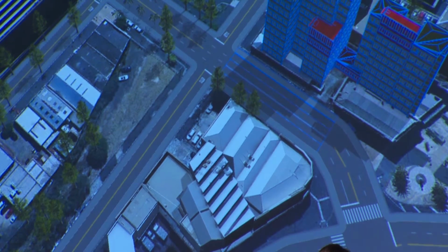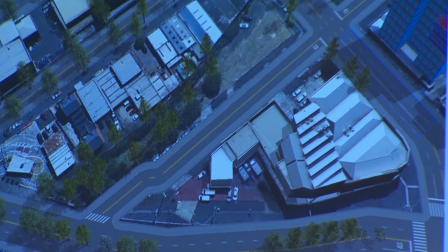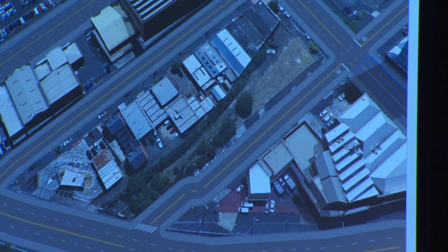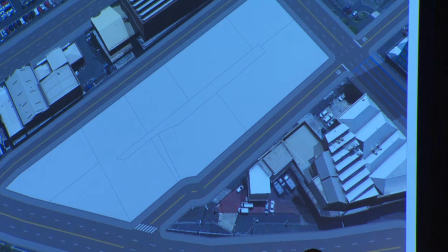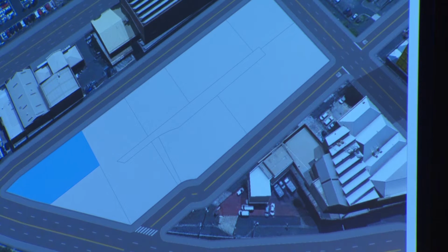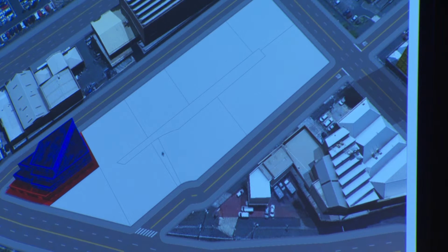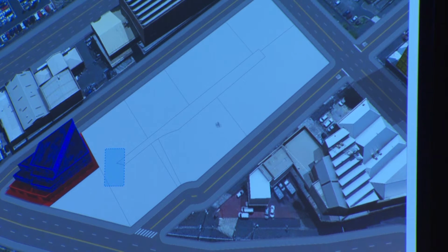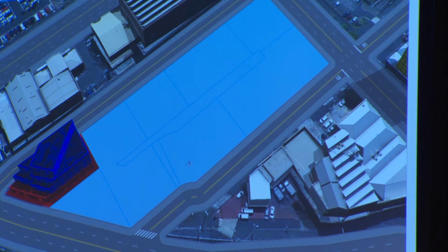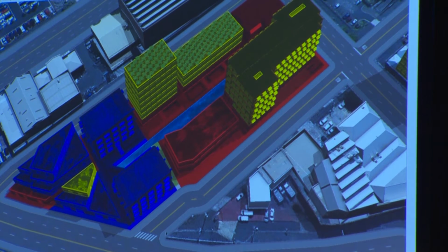Now, as before, I have this other parcel here that I wanted to develop. But rather than manually create buildings footprint by footprint, one of the things I can do is ask CityEngine to automatically subdivide that available lot into blocks, and then have it apply the same rule that I just used on that other building to generate a 3D structure. And I can do that for all these parcels, to rapidly create a potential 3D model.